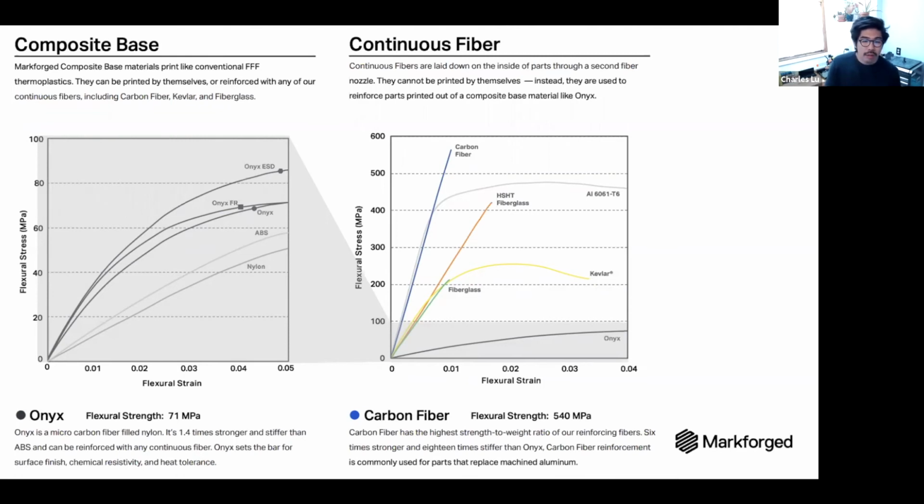Ease of adding internal metal components during the printing process. It's very easy. Eiger lets you pause the print at a specified layer, and then you can take the build plate off. This part actually finished, but if I had not finished, I would have taken it off, put it on my workbench over here, pressed in some nuts, and then started printing over. If it's a metal insert, nylon doesn't like to stick to metal, so I would first apply some glue to the top of that so that it can print over. But it tends to be very easy to do.